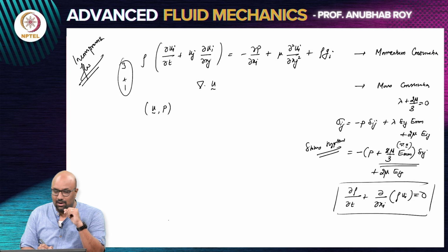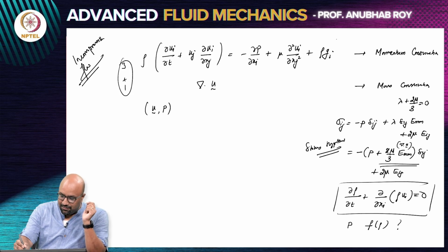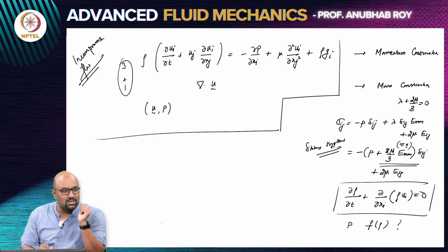But that would not be purely sufficient, because you need to give a relation between pressure and density. How is that related? Do you use an ideal gas equation of state, or do you have something more complicated? So, you need an additional equation in order to close the whole system, that is, how is pressure now related to density. So, we will keep our life simpler, because there is enough to learn and do here, which is treating incompressible flows, understanding what incompressible flows actually are.